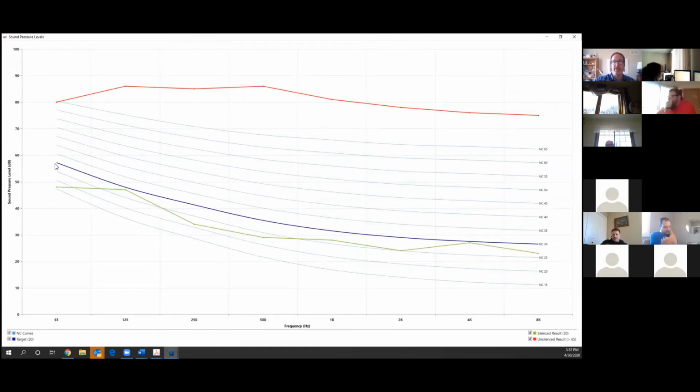Now, for you consulting engineers who review shop drawings for silencer manufacturers, let's say that you laid it out with one manufacturer's price, but then another came in and their insertion loss was off by 1 or 2 in the 500 hertz octave band. Should they be rejected? No, they don't need to be, as long as you know what the path is. The flip side of that is if you change the fan, you may have more or less octave band requirements to satisfy the equation. So if anything, you may need a little bit more silencer to accommodate for this manufacturer's sound performance and that manufacturer's sound performance.